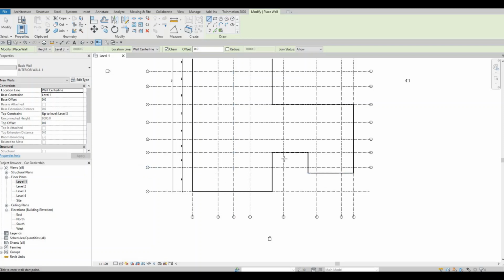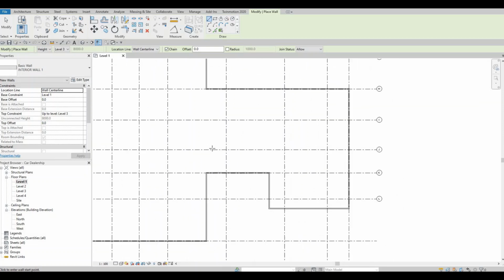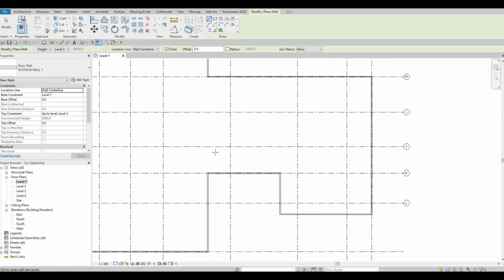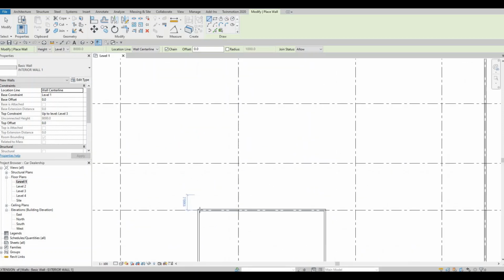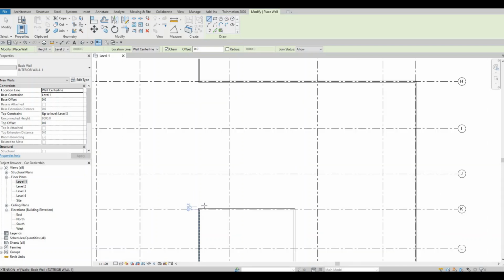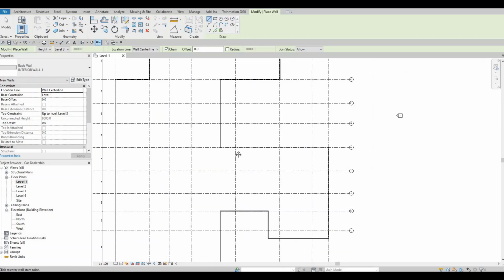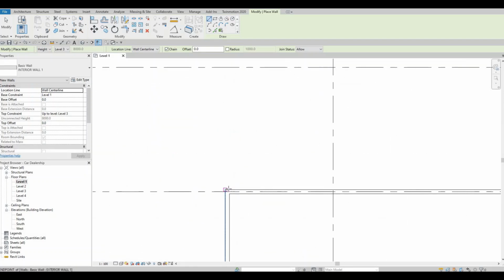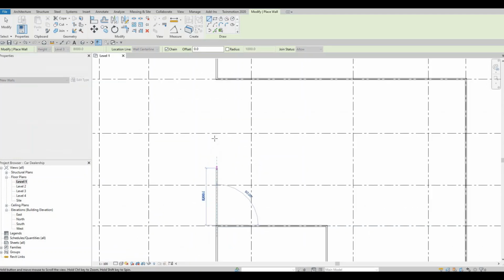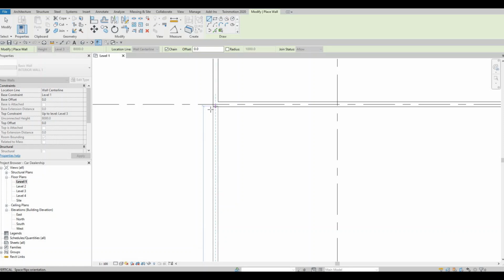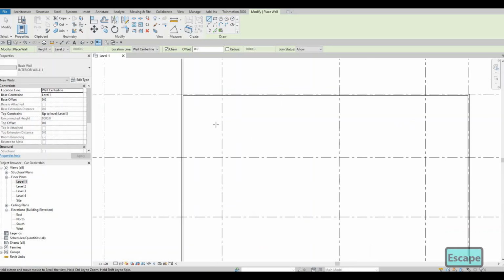So here we have our interior wall. Let's zoom in on this part. Like I said, the car will enter here, service area, they're gonna be assessed, and then they're gonna be pulled out from here to service bay 1 or 2. So here I'm just going to extend this. Luckily we're going to maintain the thickness of the wall to 200, so we don't need to align all of them, but it's easy to align.